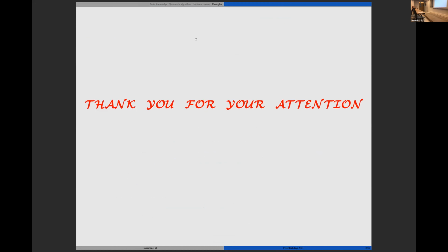Everything you did, can it be generalized to 3D? Yes, it can be generalized to 3D, and also the Coulomb friction. I presented the static case. In real life, the Coulomb criterion depends on the path. Therefore, it depends more on the velocity than just the displacement field, but it can be given as a sequence of static Coulomb criteria.